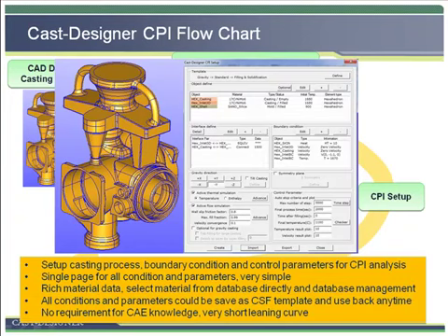Cast Designer uses a template and objective concept for CPI setup. This makes the setup very simple and makes part exchange easy for an existing CPI model. At first, the user needs to select the casting process, such as investment casting. The template for each casting process is defined inside the software.